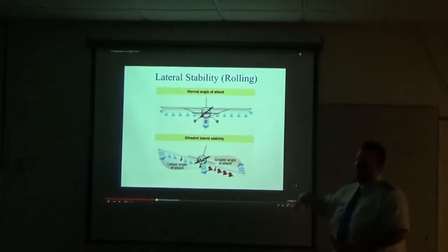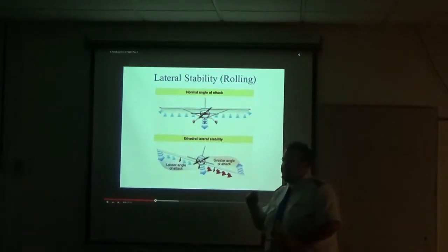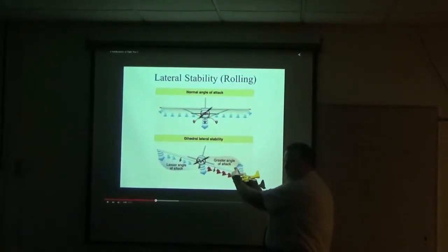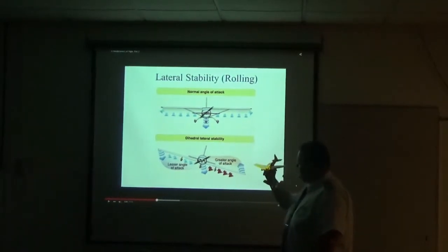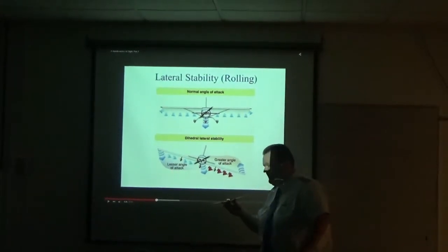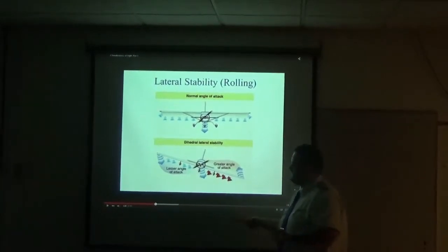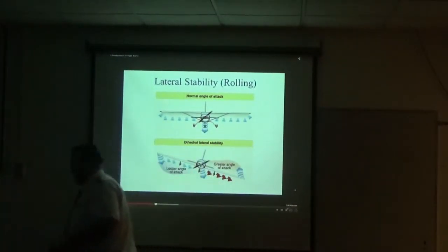Anyway, the other type of center of gravity issue that's not as bad, but still not good, is a forward center of gravity, where it's forward past where the normal center of gravity is supposed to be. Usually, that doesn't happen too much in most aircraft, because most of the time, the center of gravity is right where the engines are. Like especially on the Cessna, like this guy here. You get the side cut that we had earlier. That was a better picture.